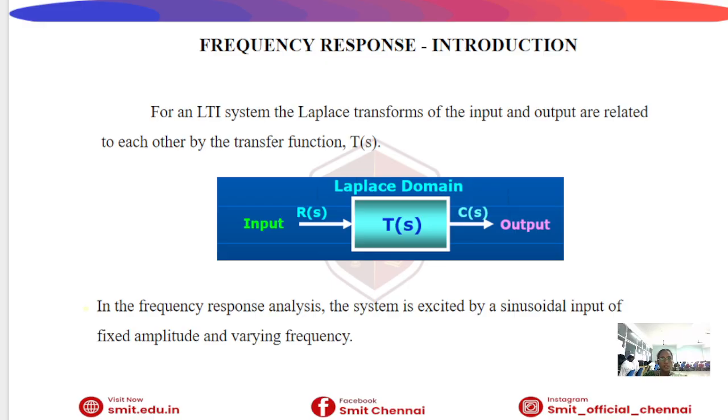Frequency response introduction. For a linear time invariant system, input and output are related by the transfer function T of s. In frequency response analysis, we apply a sinusoidal input and observe the steady state output. So if we give a sinusoidal input to the system, we get a sinusoidal output also. So how to find this transfer function? Laplace of output variable divided by Laplace of input. Generally, in frequency domain analysis, it is Laplace of sinusoidal output divided by Laplace of sinusoidal input.